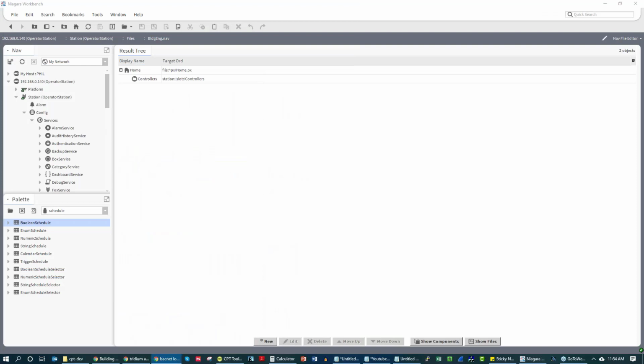The main BACnets you're going to see are BACnet MSTP, BACnet Ethernet, and BACnet IP, and supposedly BACnet Web Services if they ever roll it out. LAN is a completely different architecture. BACnet is all about structuring the messages, and the manufacturers have to implement the BACnet framework within the actual software of their controllers.